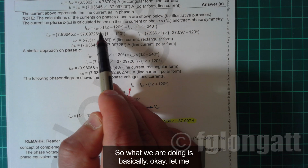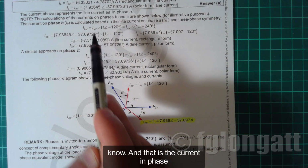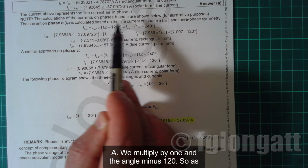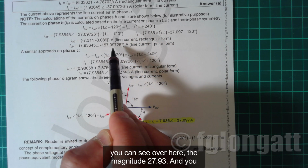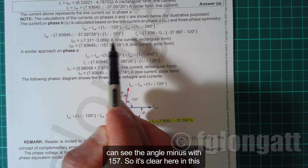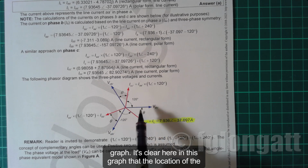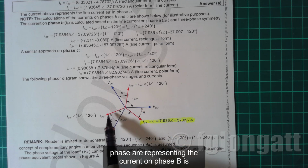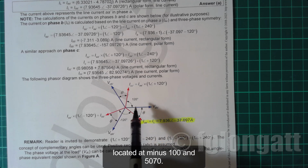So what we are doing is basically, okay, let me multiply the current that we already know, that is the current in phase A, by 1 at the angle minus 120. As you can see over here, the magnitude is 7.93, and you can see the angle is minus 157. So it's clear here in this graph that the phasor representing the current on phase B is located at minus 157 degrees.